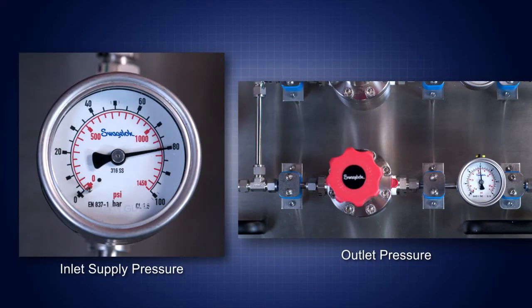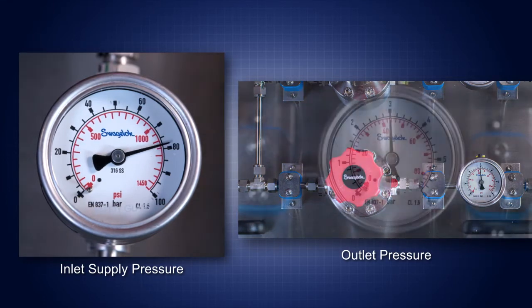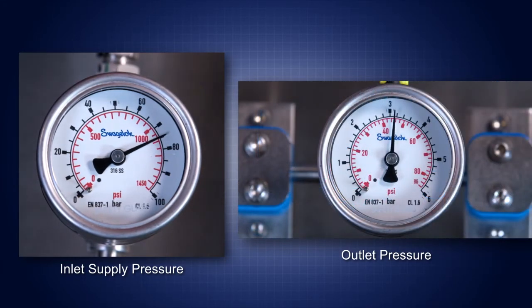As you can see, at an inlet pressure of 80 bar or 1160 psig, the outlet pressure is 3.0 bar or 43.5 psig. Decreasing the inlet pressure to 70 bar or 1015 psig results in a higher outlet pressure of 3.3 bar or 47.9 psig.